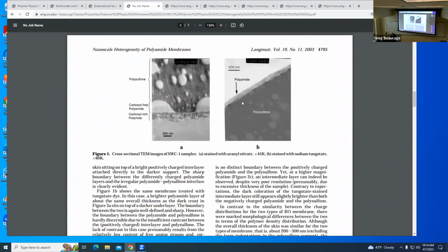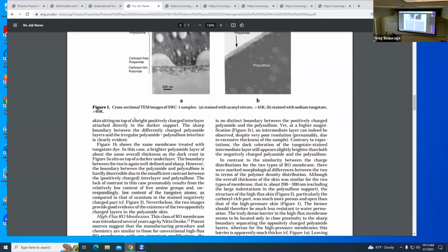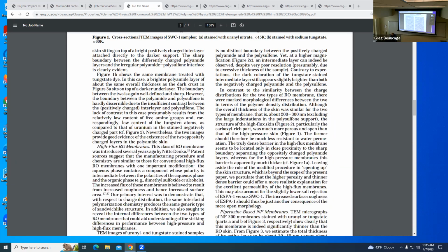Anyway, so these membranes, polysulfone is this tough, temperature insensitive industrial polymer that you can hit with a hammer and nothing happens to it, like the prison plates. Polysulfone, you can't make a knife out of them because you can't break it. Then you can put a layer of this polyamide, interfacially polymerized, onto the surface, and you make this separation. If you make porous polysulfone, then the stuff flows right through it. Then this 100 nanometer polyamide layer is a transport layer. That's where you're trying to do your separation. And then you have this really tough polymer to hold it.